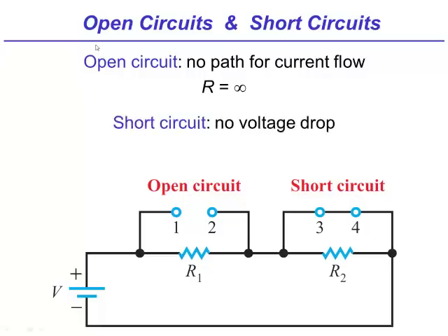A short circuit basically allows any kind of current, as much current as can go through there, depending on the dictates of the circuit, but no voltage is dropped across here. So this basically is just a perfect wire if you think about a short circuit. It completely and ideally connects this node to that node. And we'll see repercussions of this later when we do circuit analysis, but it's essentially the dual of the open circuit. In voltage, this is the dual in current. And again, when we start doing resistances, you'll see that there's zero resistance to current flow. It's a perfect short circuit. And the ammeter of the last slide looks like a short circuit.